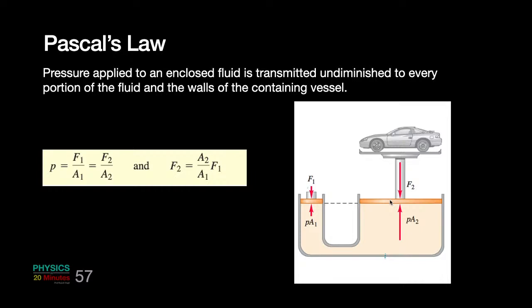Vinod, if you remember, car brakes are not at the same horizontal level. Or even, I mean you can argue car brakes to be at the same horizontal level because the brake paddle is at the foot, but when disc brakes are applied in motorcycles, most of the disc brake controls are the hand brakes, which are much above the actual disc which is placed at the wheels. So it does not matter. Pascal's law, height doesn't matter. Even if the fluid is in a tube which varies in height from top to bottom, you apply some extra pressure at the top, that extra pressure will be transmitted all throughout the fluid.